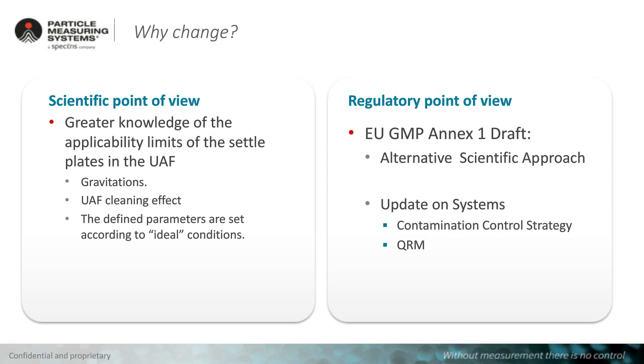And then the regulatory point of view is the EU GMP Annex 1 draft from 2017, which we hope will finally be released in 2020. It gave a clear indication that we should now use scientific approaches and scientific understanding based on risk-based approaches under a quality risk management approach to really review the data and the methodologies you're using for each sampling point.